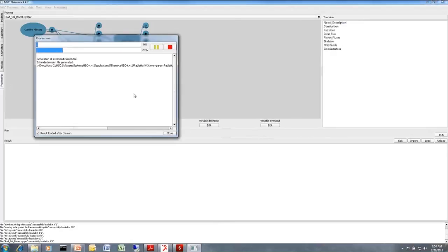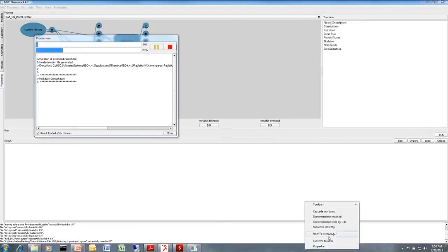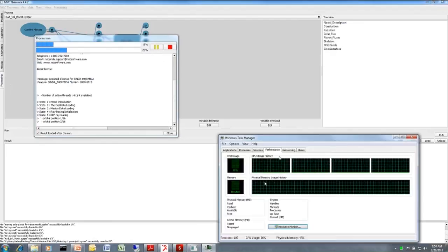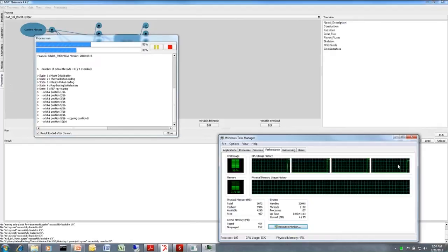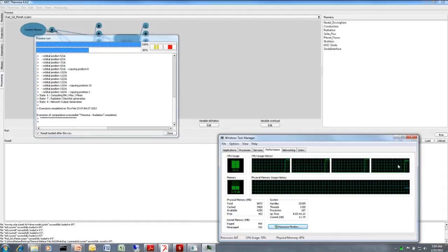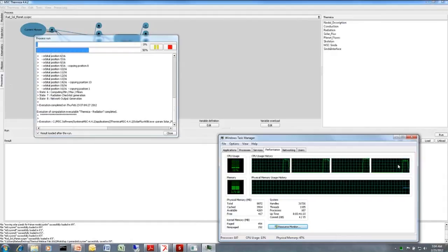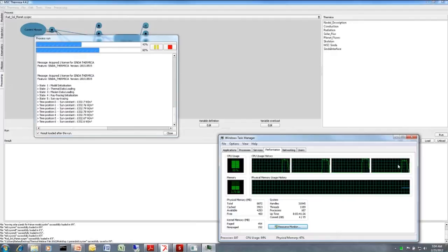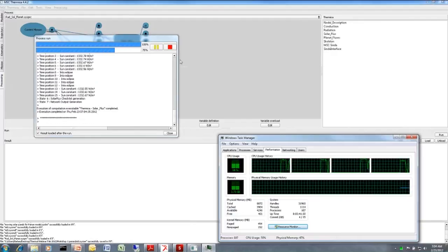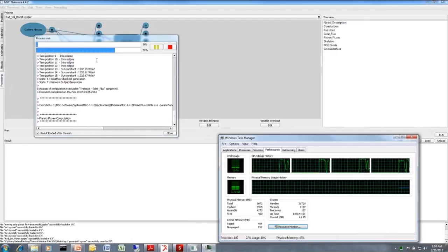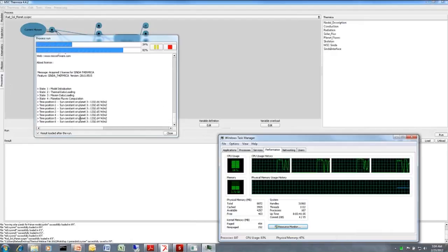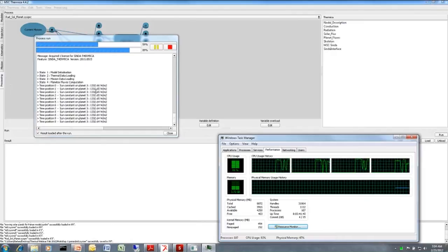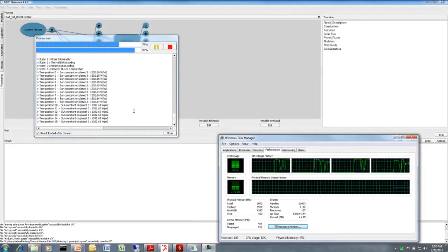Let me just run and do the computation, which takes maybe less than a minute. And as this is running, I can pull up my monitor, and you can see it's running on all 4 cores on my quad-core machine here. So Thermica runs in parallel. Our SindaRAD fast Hemicube code also runs in parallel if you have a 4-processor machine, or 8 processors, or 2 processors that run faster. And it's computing all the solar flux, view factor, solar flux, and now the planetary flux. And it's using a pretty complex sun model. When you get close to the sun, the rays come off at different angles.